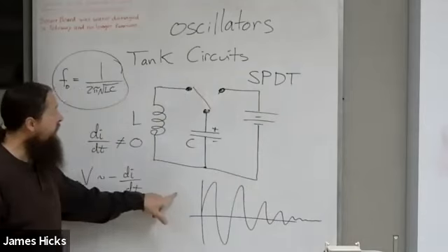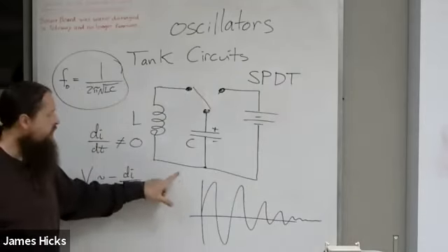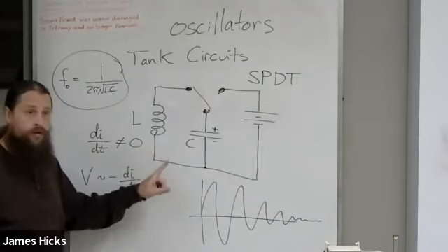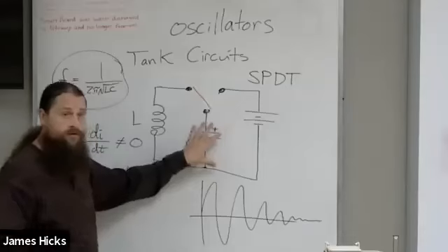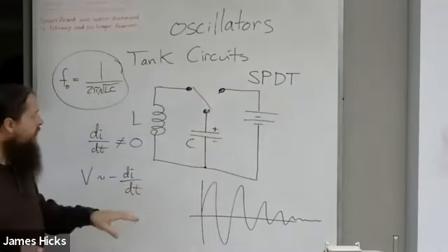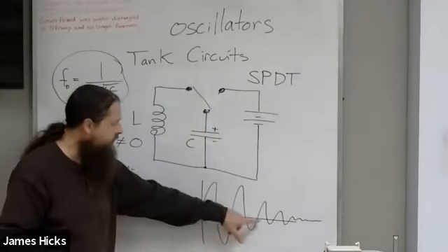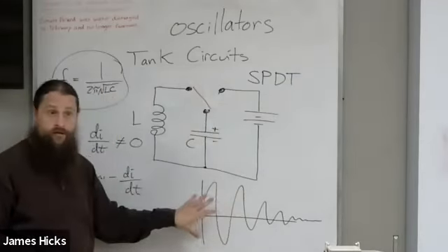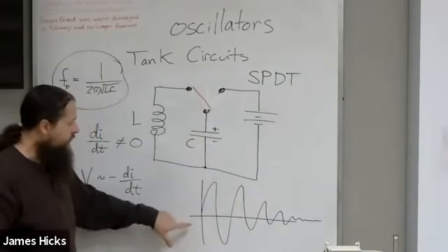That's why, to make an oscillator that has a continuous output, you need to, one, supply it with energy to minimize these losses. So that's the amplification part. And two, you need to supply the energy back in phase with this. That's the feedback and phase part. So that's all the ingredients I need for an oscillator.